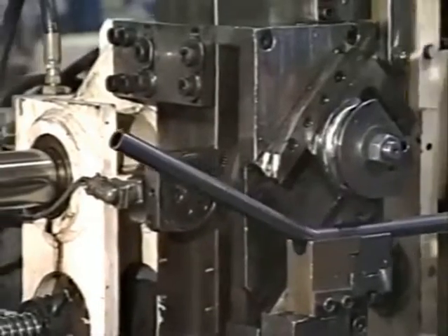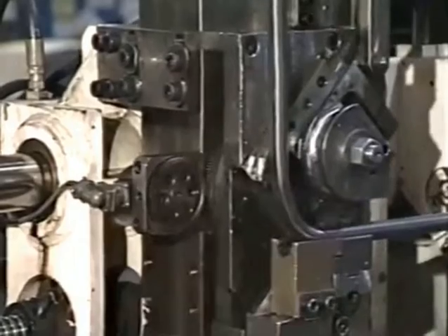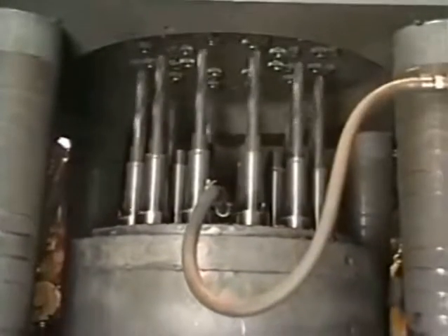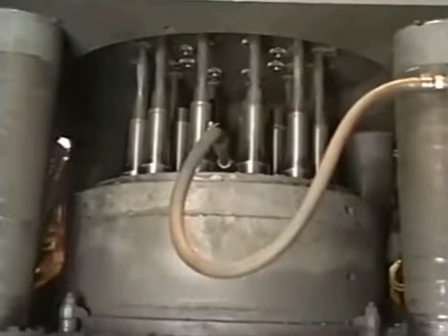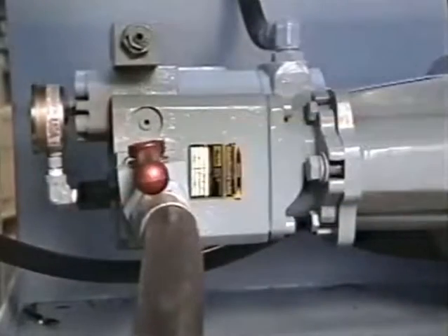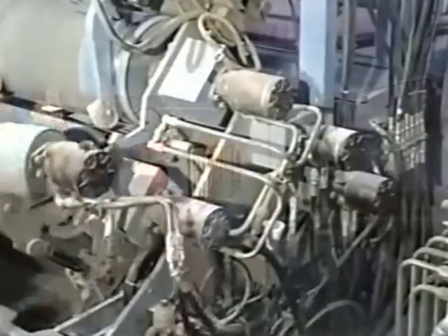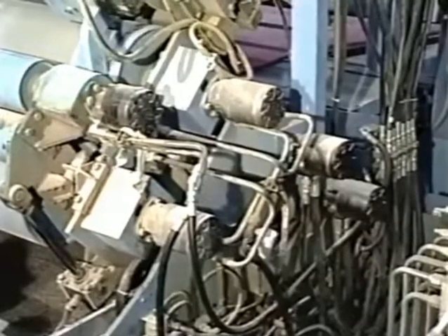How fast an actuator operates depends on the rate at which it is filled with fluid. In many hydraulic applications, it is necessary to regulate this rate, that is, to control the velocity of actuators. One way to accomplish this would be to change the output of the pump. But this would affect all parts of the system, not just a specific actuator.